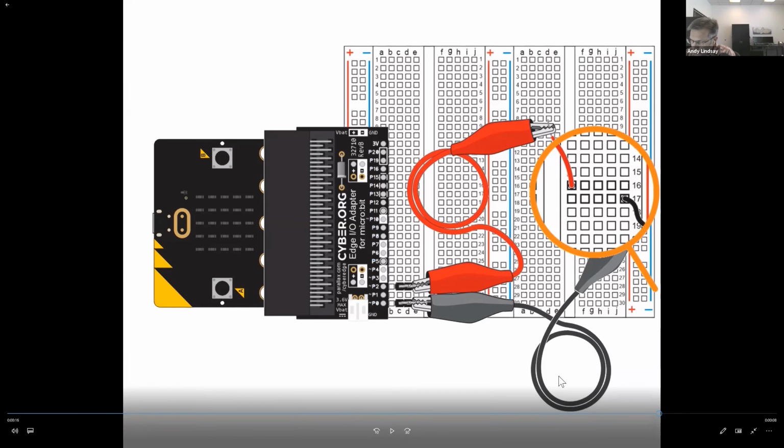And the Microbit overall is pretty robust and difficult to damage, but the main thing most electronics teachers harp on their students about is disconnecting the power before they make any changes to a circuit. So we always want to have the power disconnected before we start plugging and unplugging jumper wires.